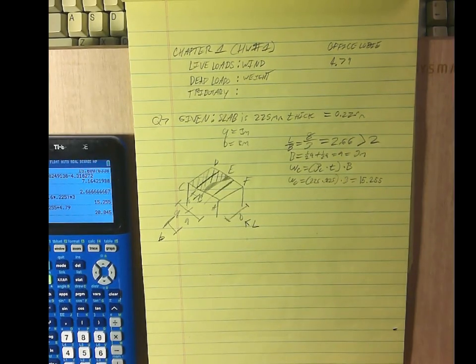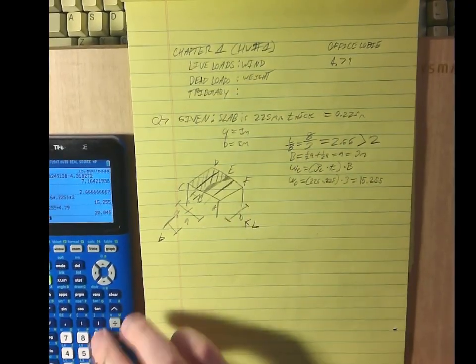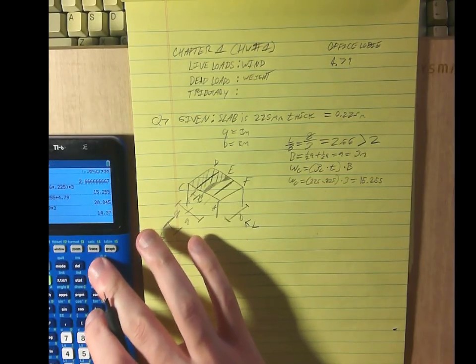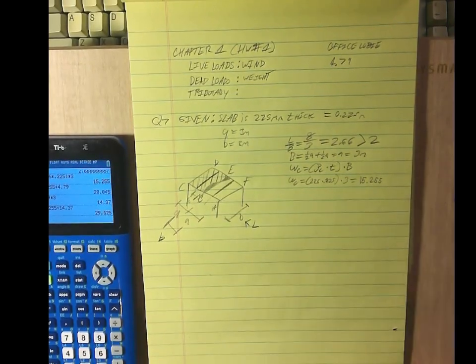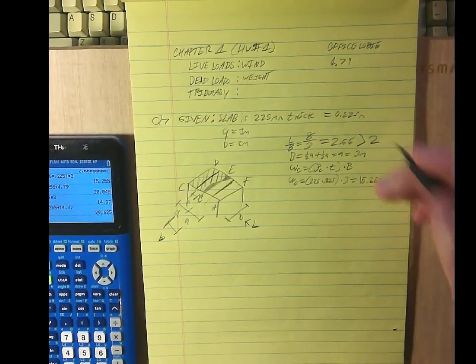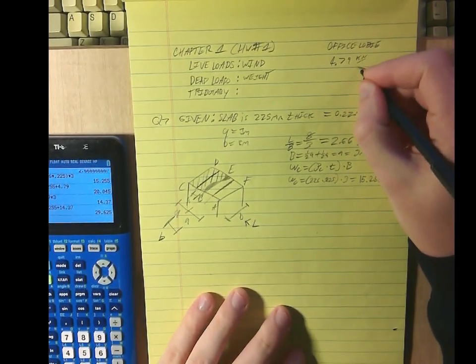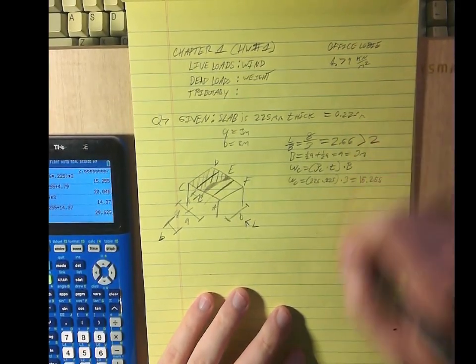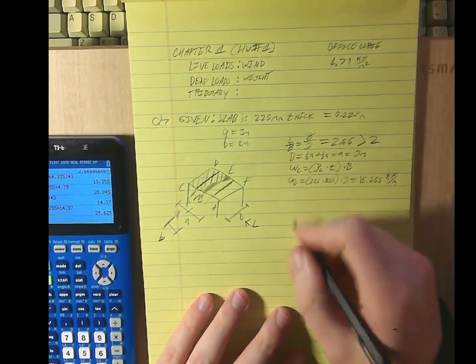We gotta do dead load plus live load. Oh, the live load right here has to be times 3 meters, probably? 4.79 times 3. When I add those up, it's going to be too much, right? No, that is the answer. Okay, I got it. For office buildings, the live load is 4.79 kilonewtons per meter squared, and we have this in kilonewtons per meter, this is our dead load.